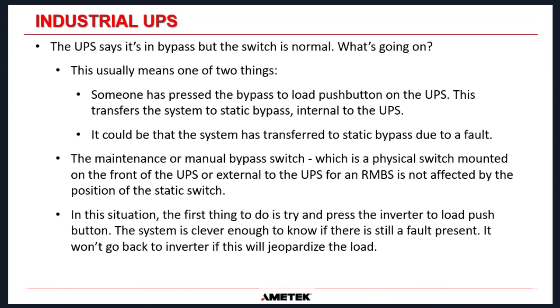It doesn't care. Okay, it's just a switch. So in this situation, the first thing that you should always try to do is press the inverter to load button on the UPS. And you have to understand, there's a lot of logic built into a UPS, and it is clever enough to know if there is still a fault inside the UPS present. So it will only go back to inverter if everything is okay. It will not jeopardize the load circuits.